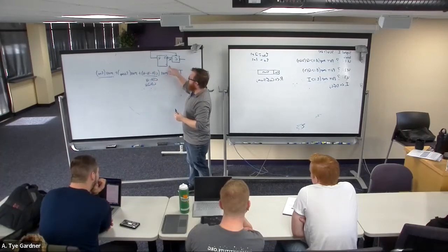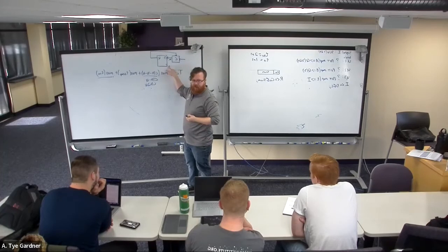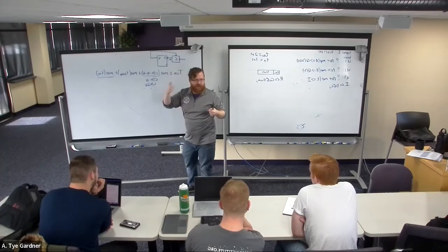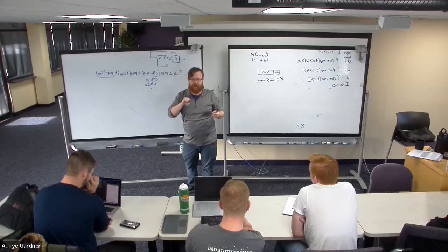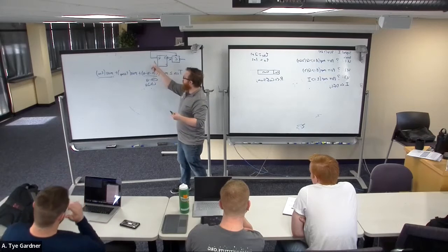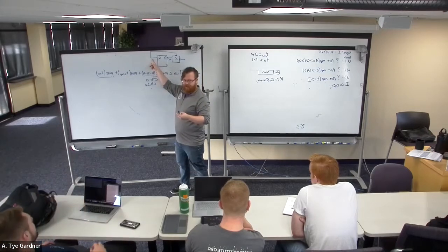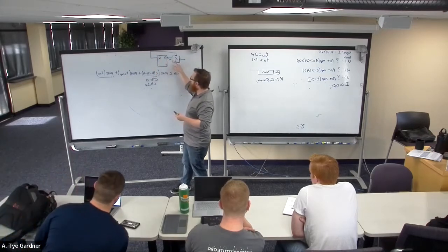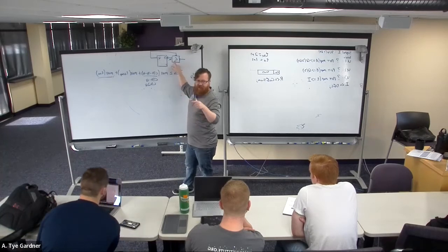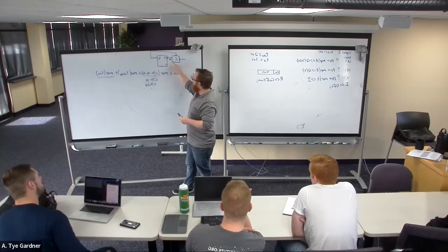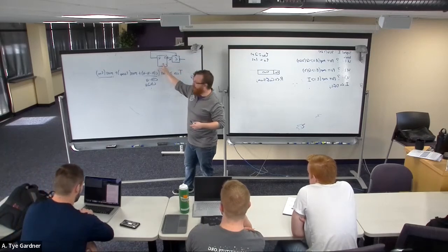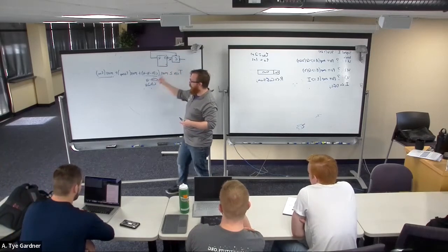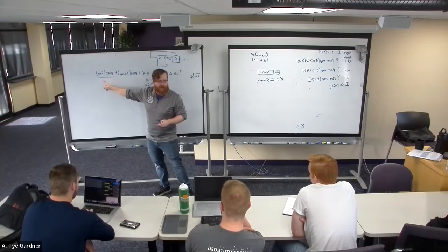So rising edge of the clock happens. And as soon as it happens, our timer has started before the next clock, right? It's now a race to see if we can update. So some amount of time later, Q updates. Then Q gets raced back around to C, and it starts cascading through that logic we designed. And then alpha updates. And then we have another clock coming. We have to ask, did we set that data up in time? Did we make it?